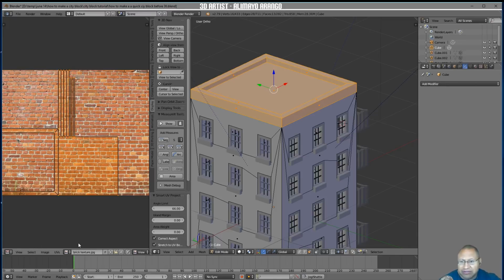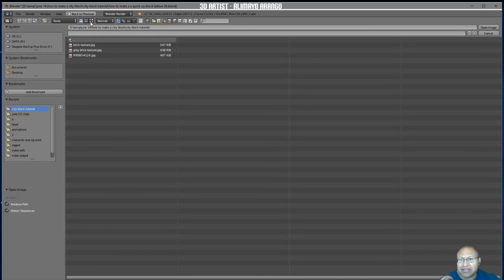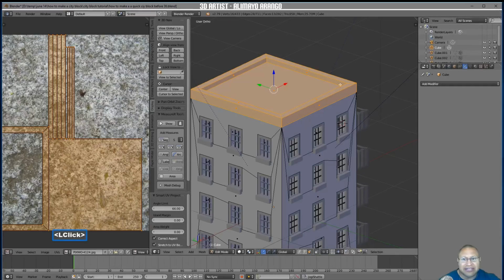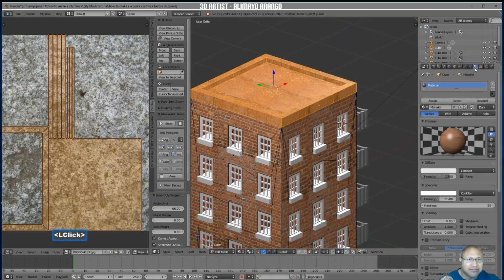And what I'm going to do is press X and then select open. I'll click these little four squares right here. I'm going to select this concrete here, and then select open there. I'm going to left click near the bottom and then select material. I'm going to go to our material tab to our upper right. We have this brick material right here, right?